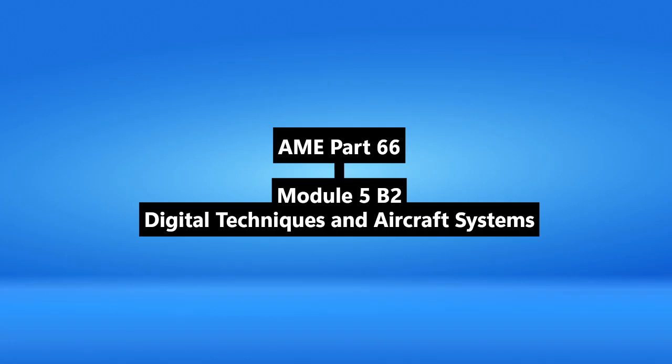How's that different? Simpler. ARINC 429 is simplex. Data only flows one way. Like a hose pipe. Good analogy, yeah. One transmitter talking, potentially multiple receivers listening on that same wire pair. It's very common for, let's say, sending data like altitude from one source to several different displays or computers that need it. Generally lower speed than 1553.